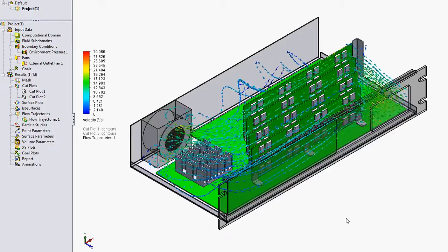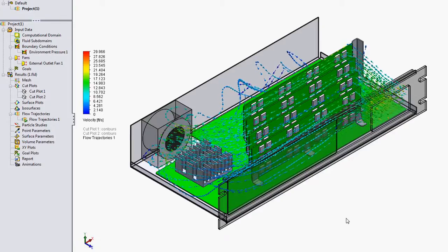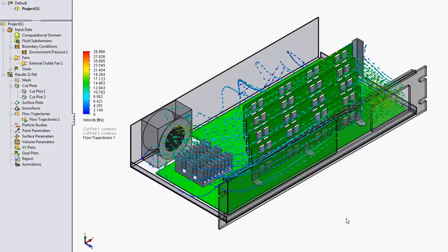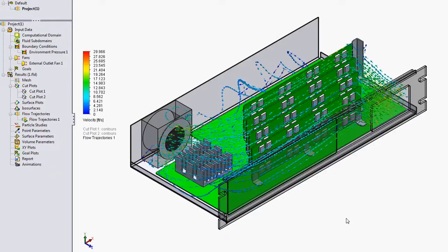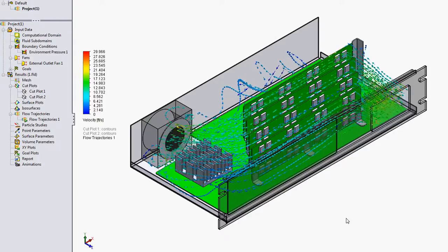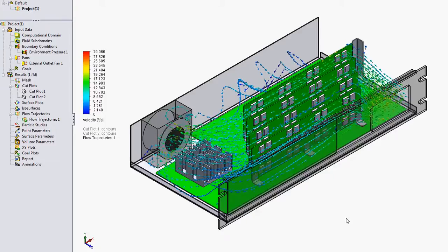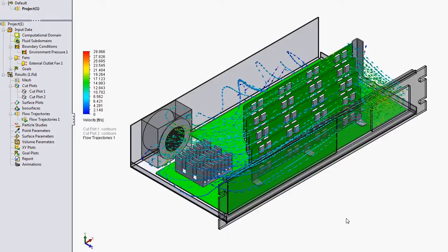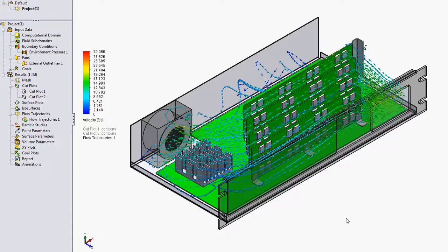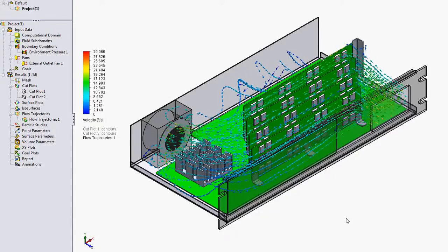Just with a grain of salt whenever you're doing this as an analysis. Based on experience, the actual curve that you will measure in reality tends to be higher. In other words, there's a greater flow resistance typically in reality than you will see in an analysis. Typically by a factor of 1.5 to 2.5. Starts off at about 1.5 and goes up from there, increasing with design complexity. Typically I'll use 2 as a personal rule of thumb.